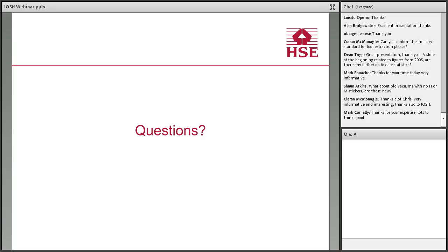For the principal contractor, what we're saying is that you need to make sure that you're employing people with the right levels of skills, knowledge, and experience coming onto your site. So, as part of the assessment process, have they got those face fit testing procedures in place? And can they demonstrate that that's working? I wouldn't necessarily expect everyone to be turning up on site with a face fit certificate, because at the end of the day, that's for that duty holder to manage and for you to have oversight to make sure they've got a system in place. In practical terms, I understand there's a real issue with agency workers sometimes turning up on site and not having face fit tests and having to get that done quickly to get people working.